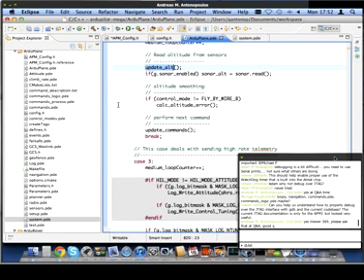One of the issues with autopilots is that the barometer readings can be quite noisy, particularly on helicopters, on multicopters, because the wind from the blades of the propellers can cause a lot of turbulence around the barometer, and that causes the barometer readings to be quite noisy. The change that we made just a couple of weeks ago to read that at 80 hertz using an interrupt-driven driver means we now get a much smoother altitude reading, which is particularly important for things like calculating climb rates, which is important for altitude hold on a copter.